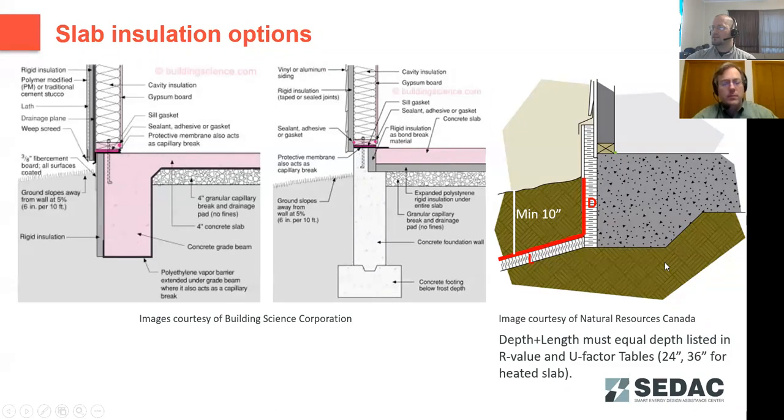In many cases, we got a question here about discontinuity in thermal insulation at interfaces of roof and wall, and wall and slab. The requirement for this insulation is that it is continuous. So if you've got some kind of discontinuity, the code would require that there be some way to either minimize that. If it's an unavoidable discontinuity, you would have to work with your authority having jurisdiction on how to comply with that. But there should be details to prevent discontinuities in your exterior insulation.